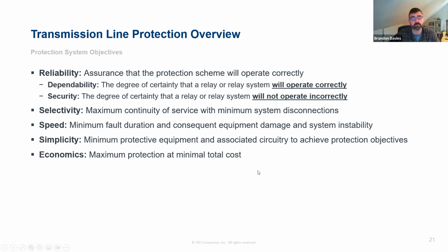Because there's a lot more constraints on reliability these days, when you go to operate your system, you need to be able to operate it for the day that you have to take that relay out of service to do maintenance testing on it. You need to cover the case where these are very robust electric devices, the relays, but they do fail. And the equipment that is giving them the information fails, or CTs or VTs could have problems.